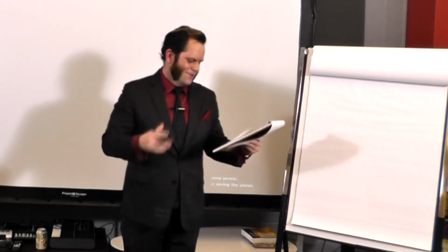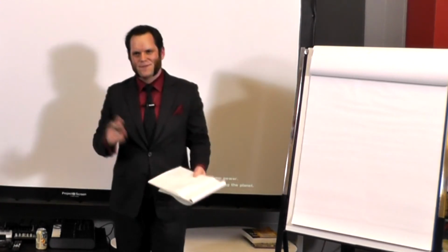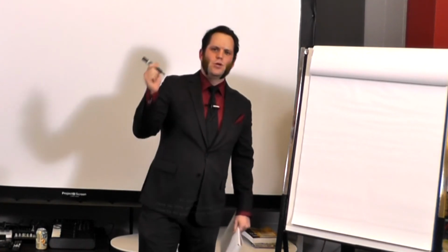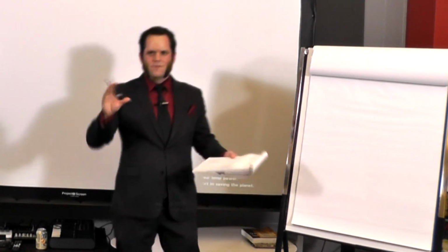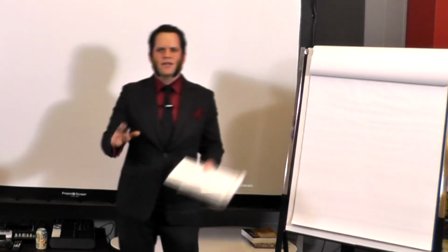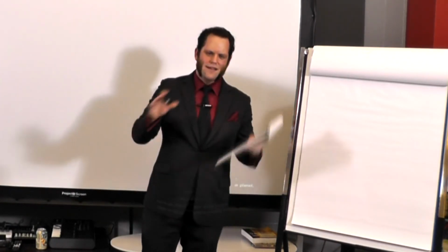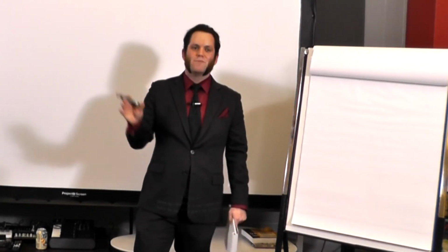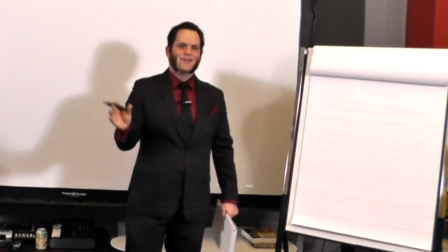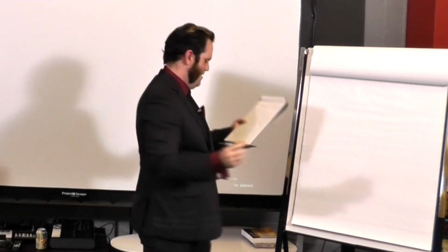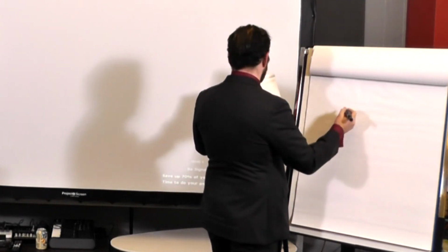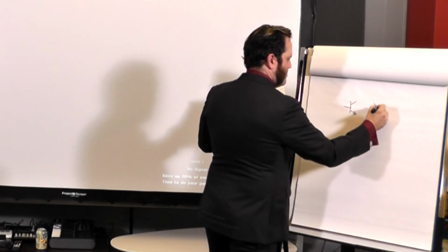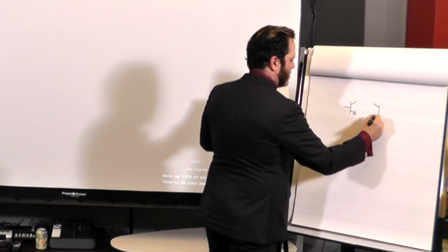So I'm going to throw some stuff at you and try to explain it as best as I can, but I'm also going to try to move a little bit fast here. We're really bad at making transistors to a certain spec. Like, we want a certain beta or transconductance in the transistor, and we're really bad at doing that precisely. However, we're really good at making 2 transistors, whatever their specs may be, almost identical. And it turns out we can do some really cool things with that. Those of you who have studied EE 201 or whatever your equivalent course number is will identify this as basically a current mirror. And I can draw.